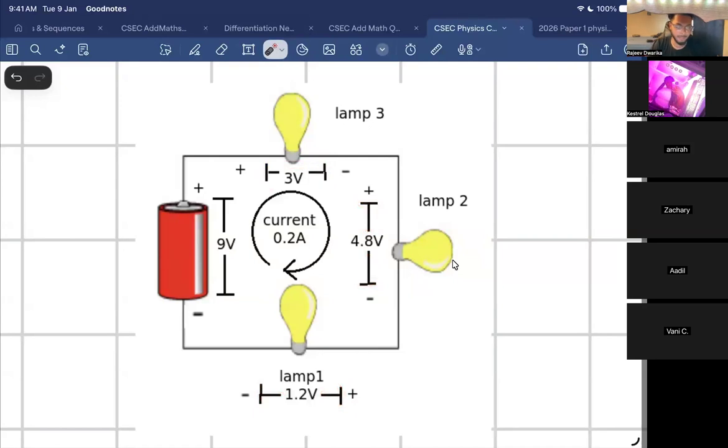The battery. Right. So Kirchhoff's voltage law. I like to remember it a different kind of way. It says that the sum of voltage drops in a circuit is equal to the source voltage. So again, 9 volts in the circuit supplied by the battery, so the sum of the voltage drops must be equal to 9 volts.